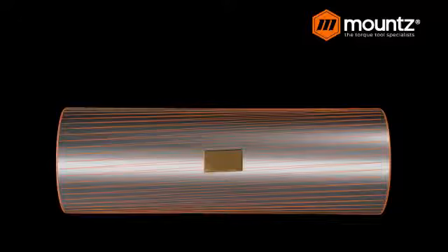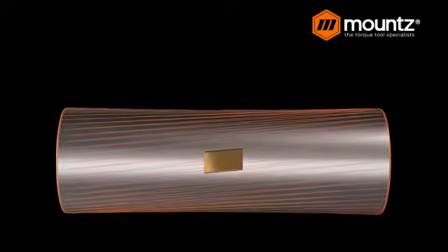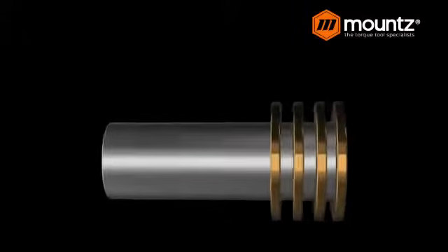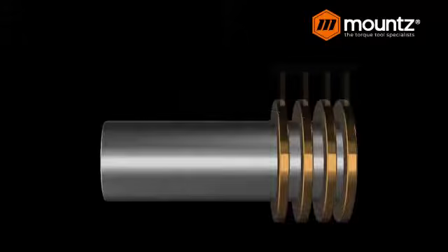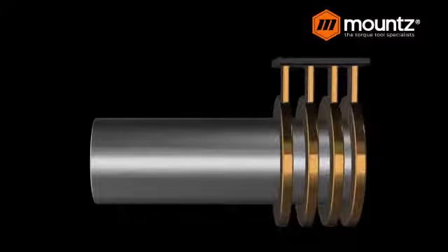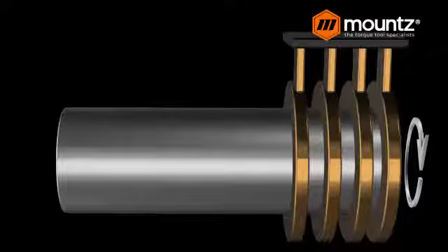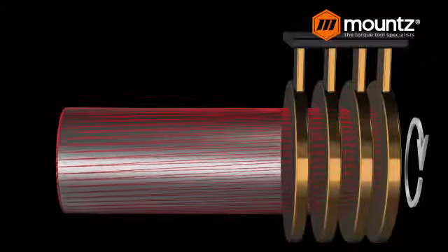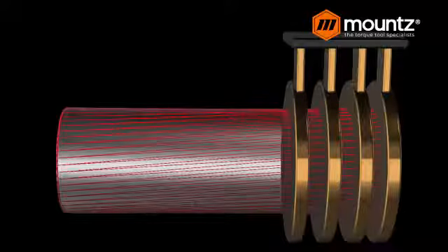That's a little different from a rotary style transducer. How that primarily functions is we have a shaft that rotates, and around this shaft we have slip rings, and we're able to measure those slip rings. As the shaft is rotated, we're constantly measuring the resistance between the different rings. As we get to the shutoff point, we get some deflection in the shaft, and now we're measuring that deflection with the resistance between each of the slip rings.